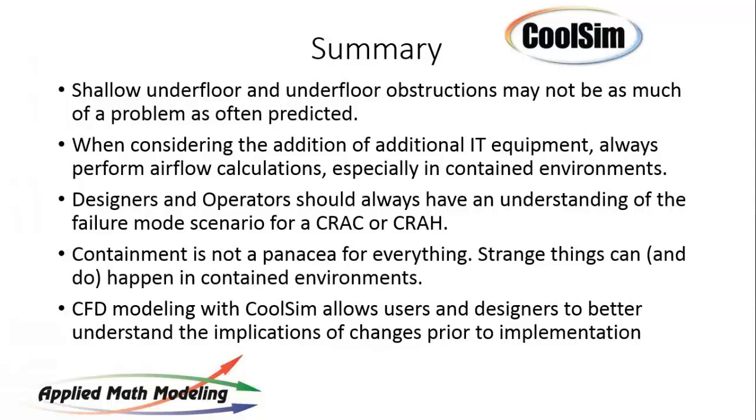But if you're tightly contained, particularly on cold, and you lose a cooling unit, the servers have nowhere to go. There's no way for them to get air. So it's important that you understand the containment in the failure mode situation prior to implementing it.